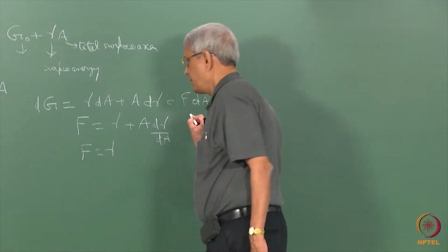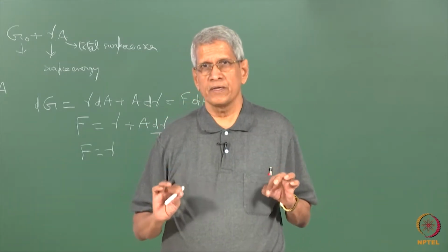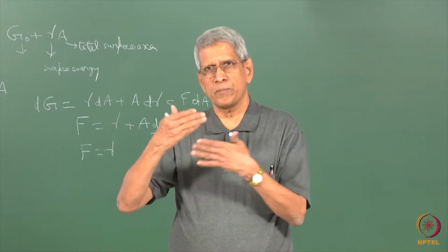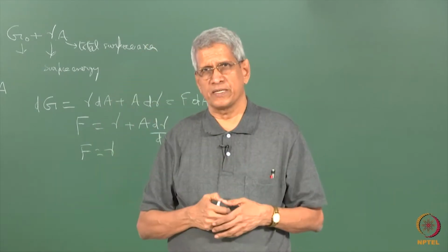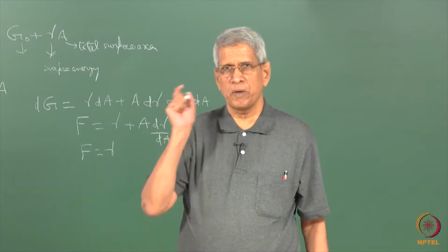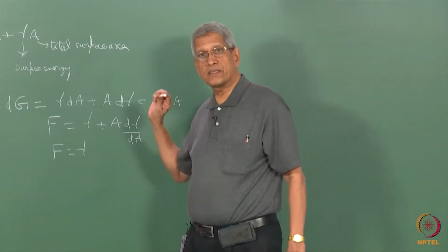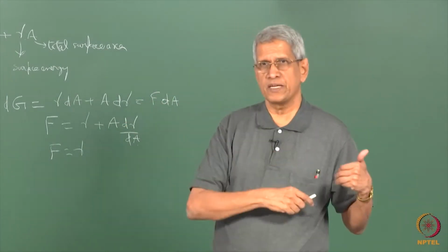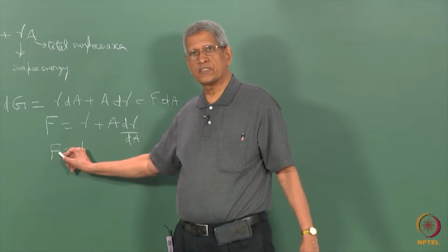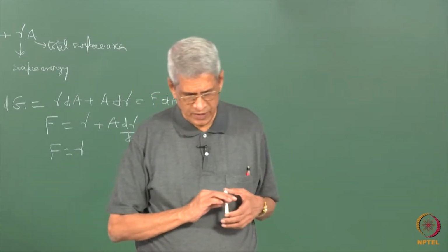But in the case of solid samples, we cannot assume that they are the same, because when we take a liquid film and try to increase its area, quickly the molecules rearrange themselves so that the surface is created. In a solid material, if you try to pull it, the atoms have to rearrange on the surface, and it may take a finite time. So if the experiment is done in a fast time compared to the time it takes for rearrangement, in such cases the surface tension or the surface force need not be the same as the surface energy. Is it clear?